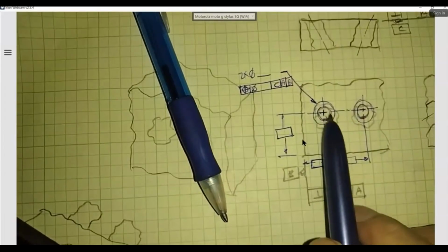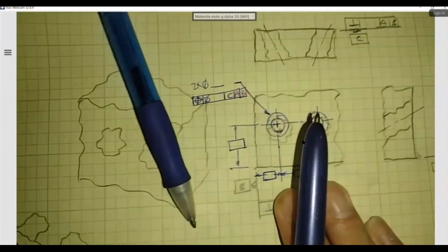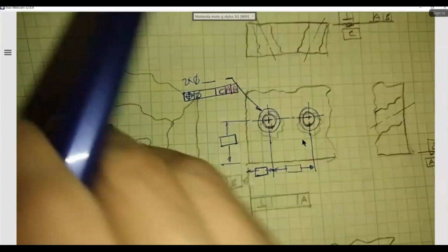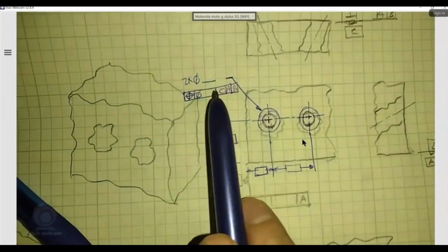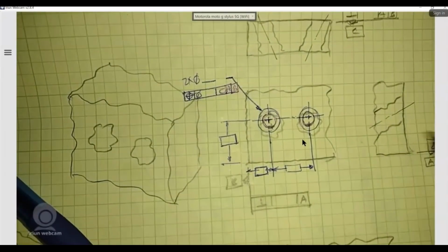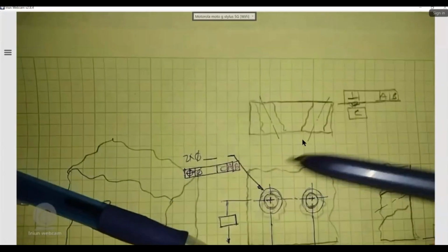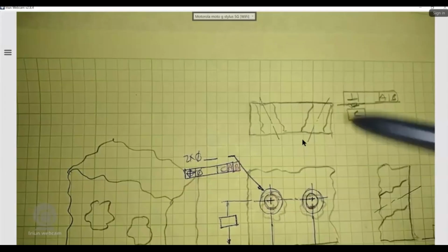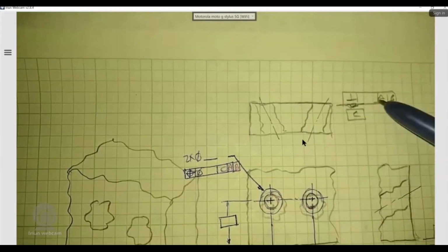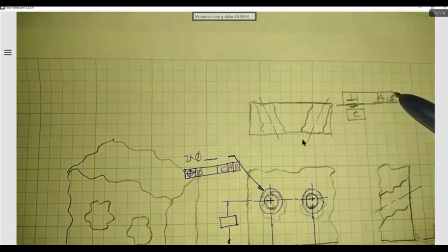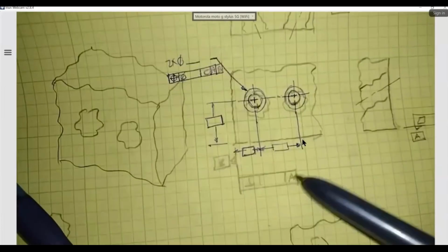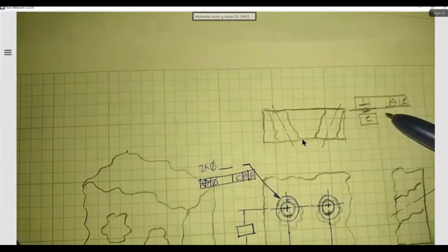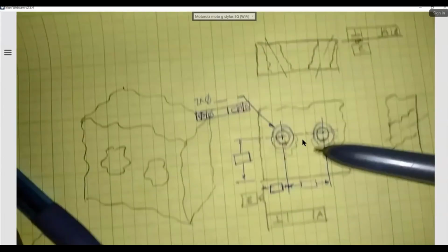Right now, I'm just grabbing the bullseye and I am defining it. The way I define it is by defining the bottom, defining the left, and defining the back. I start that way. Right. Before I actually define the bottom, the left, and the back, I had to have qualifiers that orient each datum to each other. So I have flatness, that's why I got perpendicularity. I have a reference frame now that I can refer to,